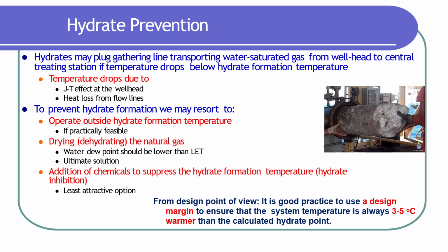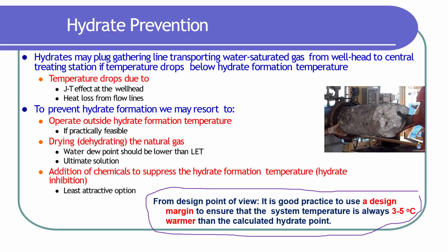Now we're going to look at the hydrate prevention, but before we start with the hydrate prevention, we need to look at one point that we need to highlight from the previous lecture, where once we calculated the hydrate formation temperature, it's always to keep in mind that we need to stay on the safe side. So as a result, we add something called the design margin, where the design margin recommends that once you calculated the hydrate temperature, for example, you add 3 to 5 degrees Celsius to keep it warmer than the